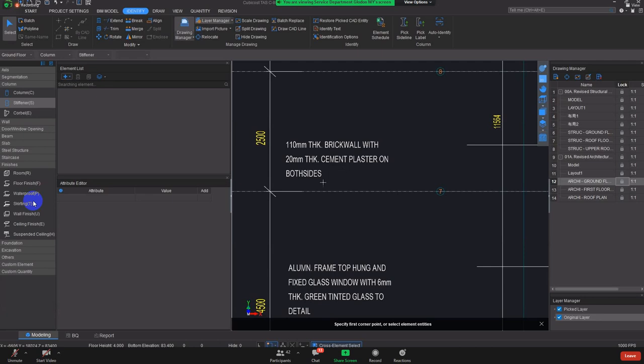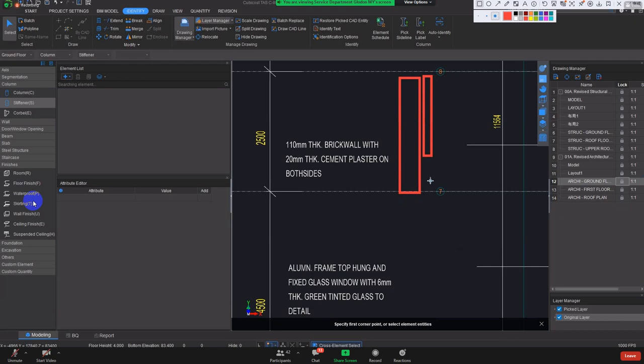And then if you want to create the plastering, you need to go to the wall finishes, and we'll cover the plastering part tomorrow. Don't worry, right? Meaning to say, this is the thickness of the wall, and you have your finishes to wall, which will be the plastering. But for the training purpose, I put it as 150. I didn't separate out 110, and also 20 mm on both sides, right?